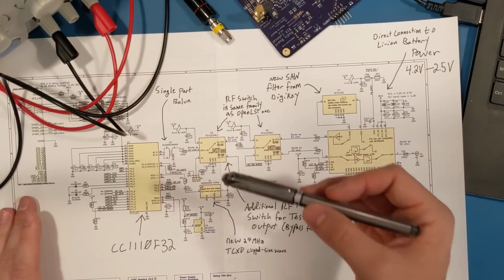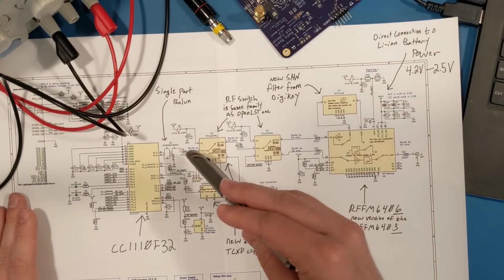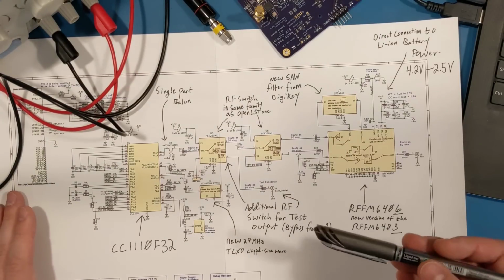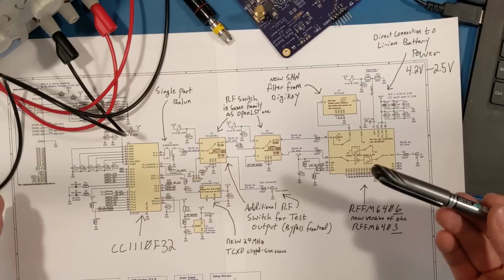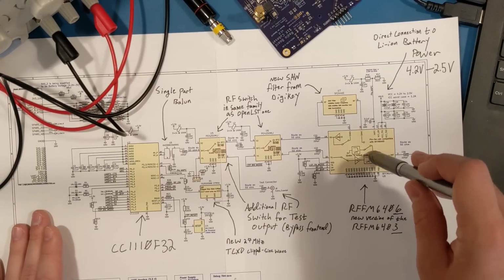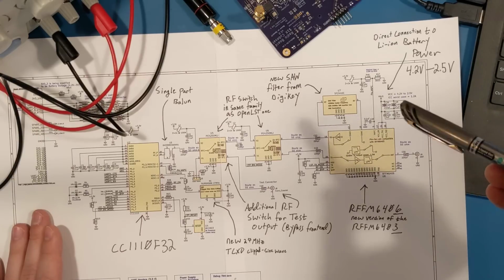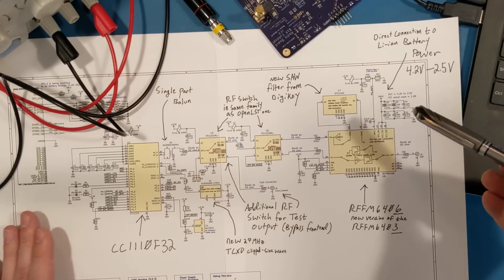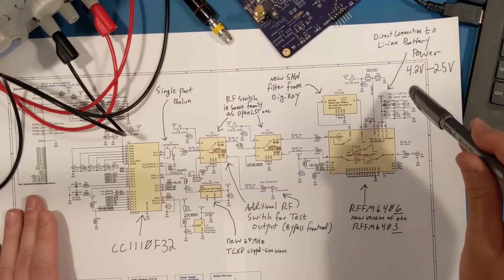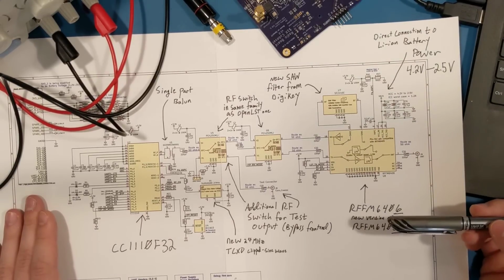The radio is pretty much a clone of the OpenLST design, except I had to swap out a whole bunch of the parts for available alternatives. I also removed the onboard 3.6 volt LDO, which converted 5 volts to 3.6 volts to power the RF front end. Instead, I connect the RF front end's high power input directly to the lithium-ion battery on board, which saves on complexity, and it seems like the RF front end was designed this way, where it accepts 4.2 volts to 2.5 volts for its high power input.